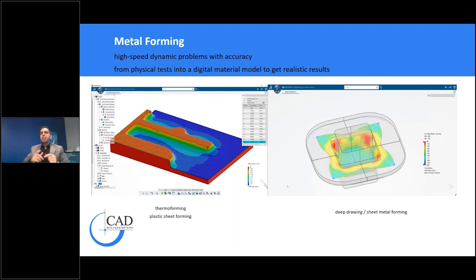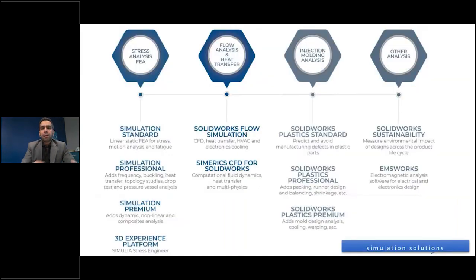This is very challenging for any other solution other than Abaqus technology, which has both implicit and explicit within the same solver. On the right is a thermal forming, and basically we can do the same sort of forming. It can be for plastics, it can be for other material in different temperatures. So thermal stress and having thermal calculations within our implicit and explicit solver capabilities are available.